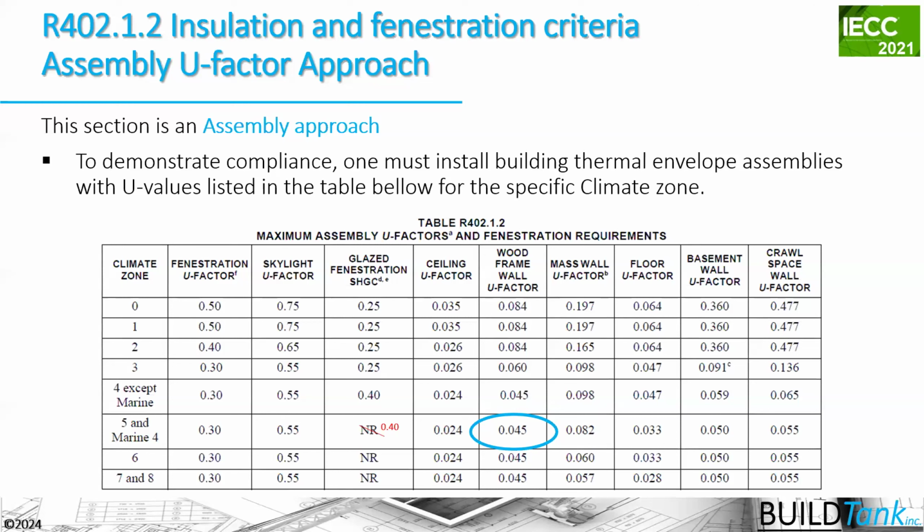That's really why we want to know the U factor of the assembly, is that we need the U factor to be able to do an area weighted U value trade-off when we use REScheck software or Energy Gauge or Ecotope software, REM/Rate software. All those different software can do that type of analysis.